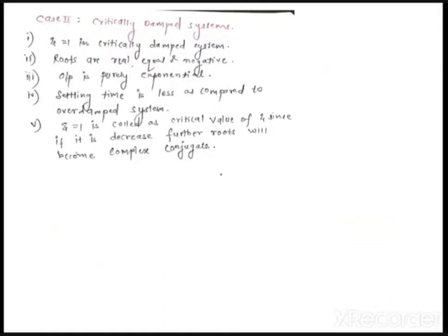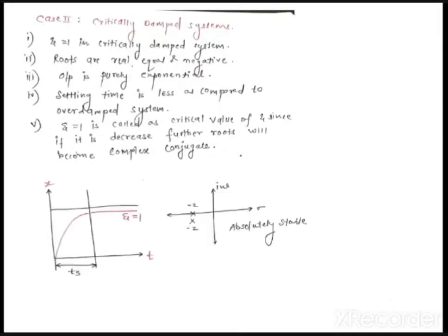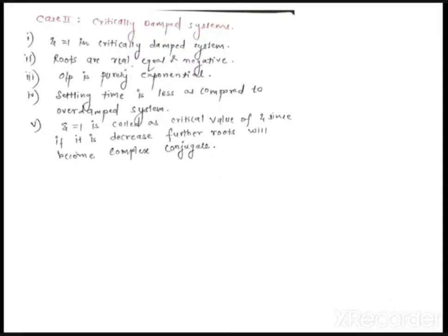Now guys, try to understand that when the value of zeta is equal to 1, what exactly happens? The roots are real, equal and negative. In that case, what was the nature of the roots? Now guys, I hope you have understood that the behavior of the system, whether it is oscillatory or exponential, depends upon the nature of the roots, and the location of the roots also depends upon the nature of the roots. Okay, so basically I can write like this. There are parameters, let us say m, c, k. m, c, k means what? Parameters of a physical system.